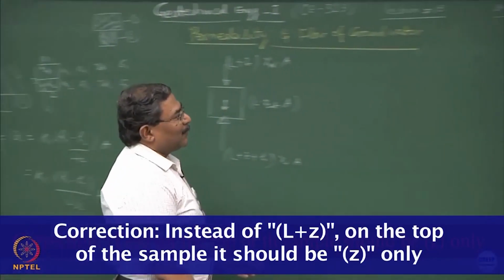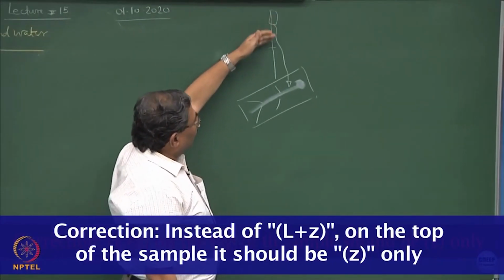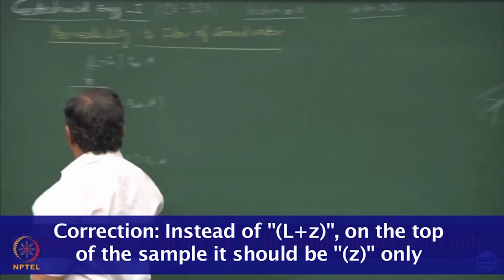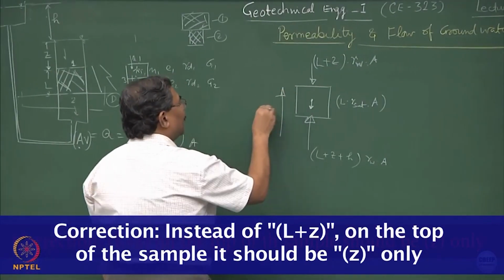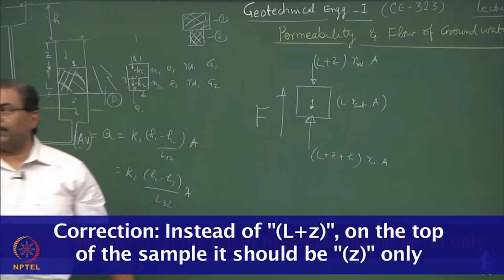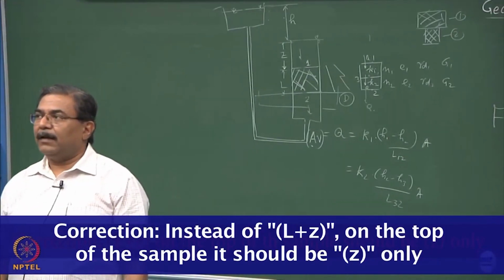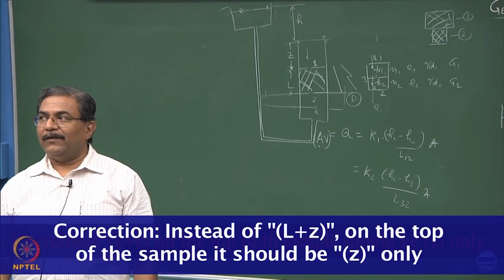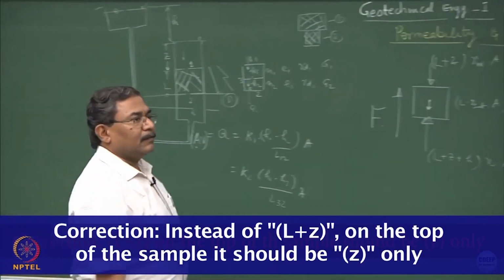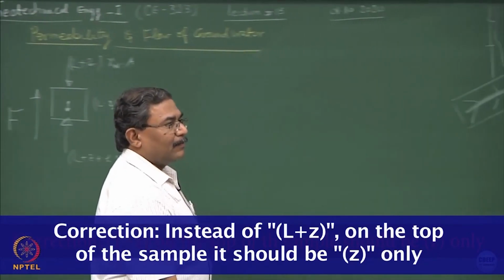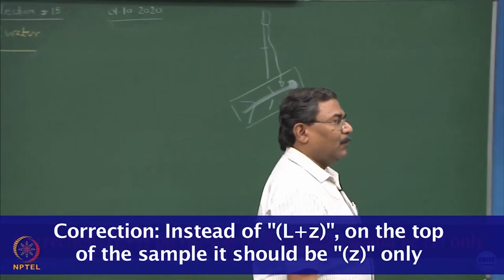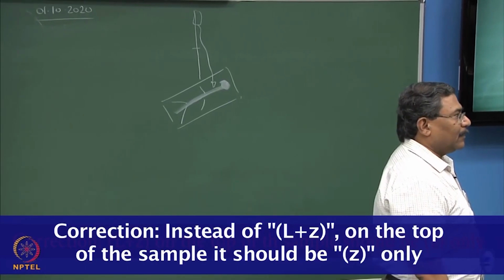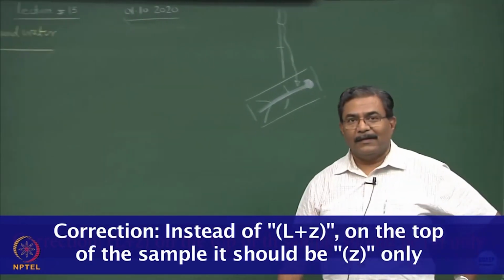Is this okay? So, if I lower it down and bring it up, I can create a force which is going to act on the system. So, this is your seepage force. Take where the seepage force is acting. What is the plane on which the seepage force is acting? You have to look at the figure.